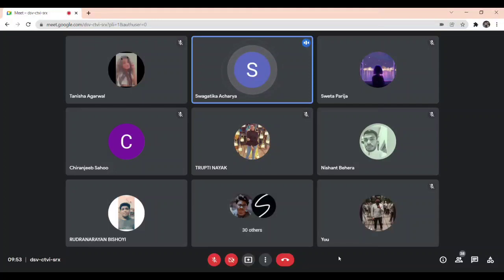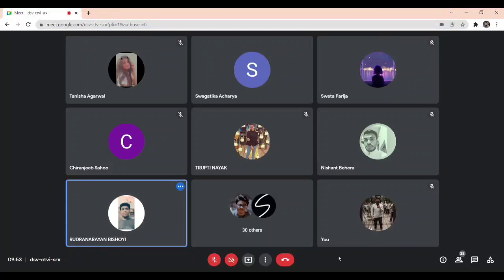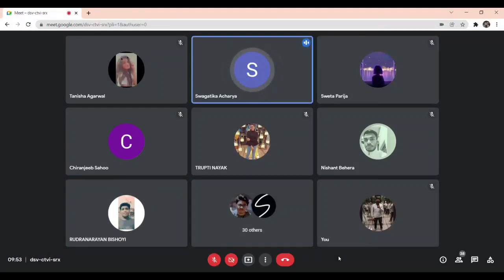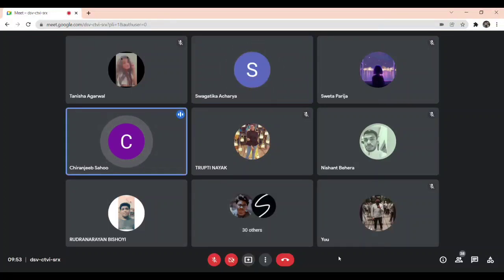Sorry, Rudra, can you repeat? You are not properly audible. V equals RL VI by R plus RL. No, I'm just asking the equation. Directly give me the equation. What will be your KVL equation? VI minus IR minus IRL equal to 0.